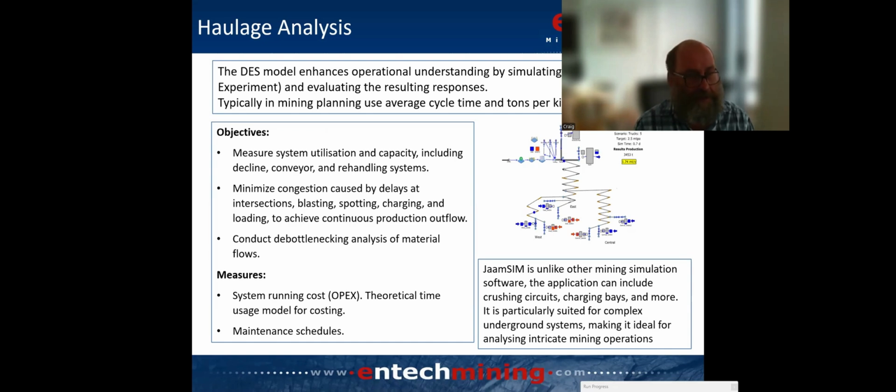And also, as we get more sophisticated with decarbonisation, we've got to consider things like charging bays and the depletion of the battery as the piece of equipment is moving. To tell you the truth, it hasn't been solved from a haulage perspective. It has been partly solved in bogging, because in bogging you're actually on the flat. But with haulage, because you're taking such a large payload up the decline, there's a lot of energy spent.